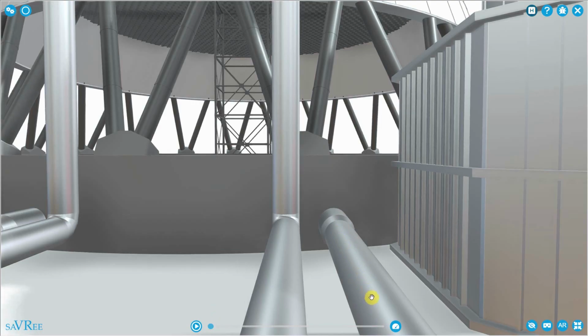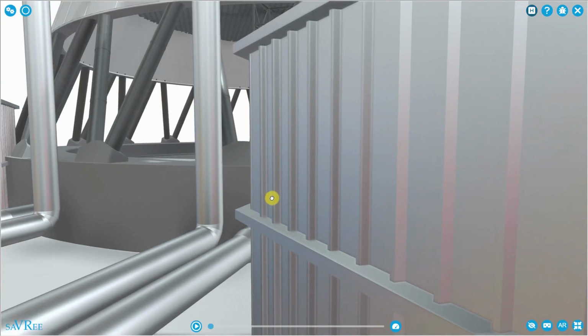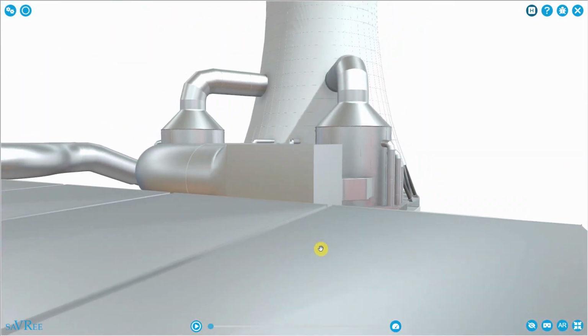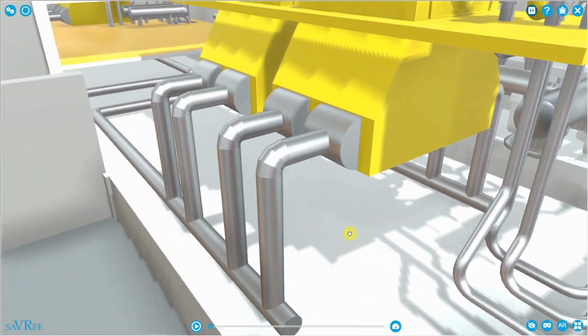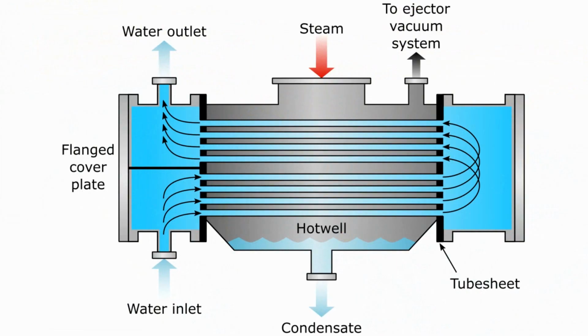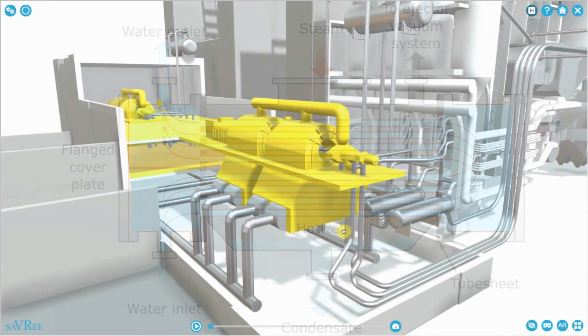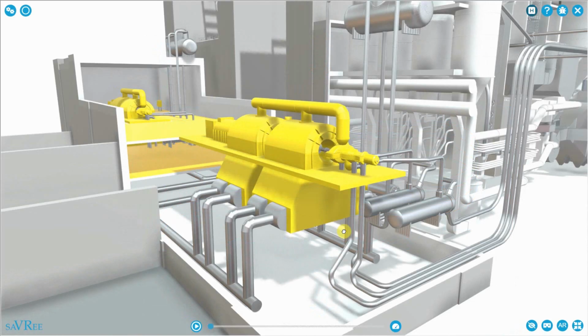So we're drawing cooled cooling water out, or cold cooling water, and we're sending back cooling water that has a slightly higher temperature. The reason we're sending it back at a slightly higher temperature is because within our condenser, when we condense the steam, some of the heat energy from the steam is passed to the cooling water, so its temperature increases, the steam temperature decreases, and that's what causes it to change state and become a liquid, which we refer to as condensate. I will say here that condensate is typically from the condenser up until the deaerator. From the deaerator, we then have feed water. After the boiler, we have steam.